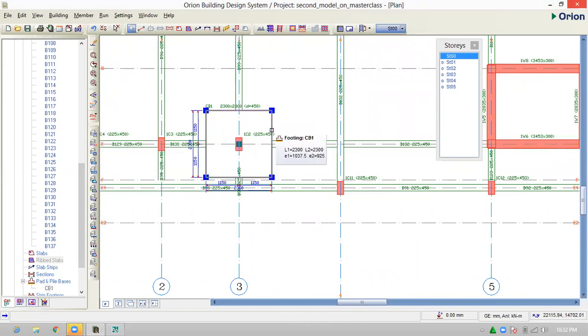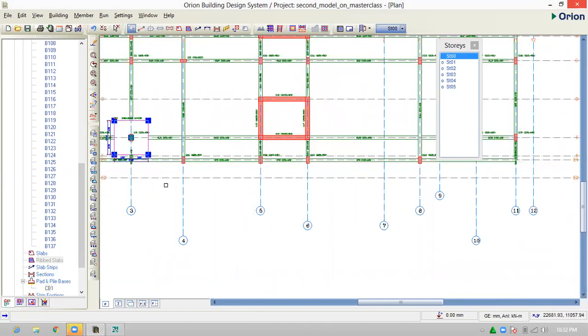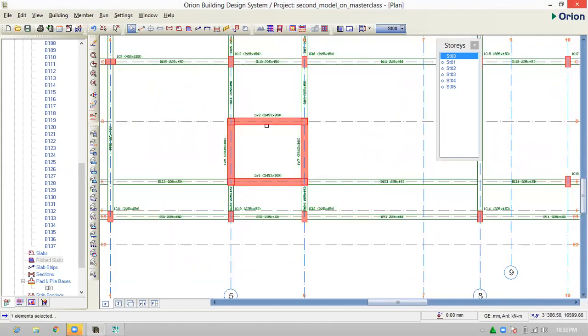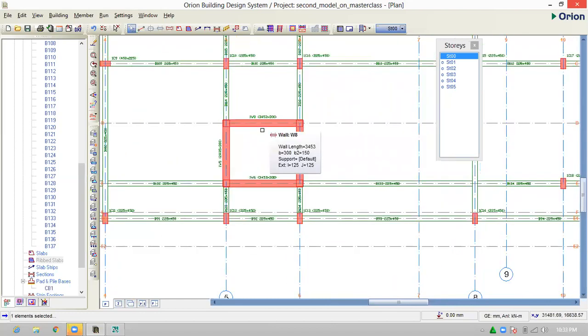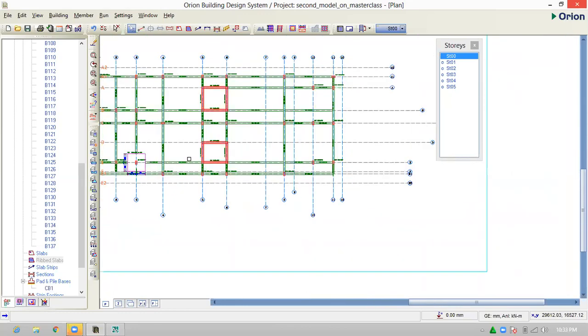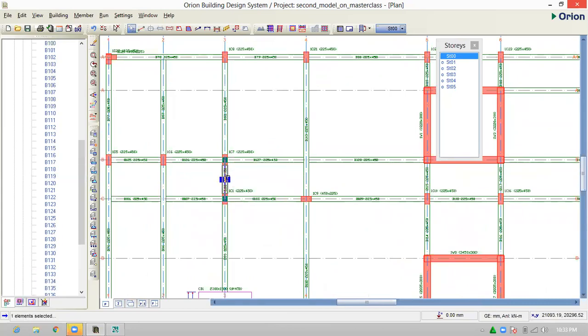Do you get it? So now by tomorrow, I'll show you how to get the details of your footing. And so now, assuming I want to add a strip foundation, I'll select this. I'll right click, select the wall or the beam. Let me say I want to use, where do I have two beams together? Okay, a beam linking two columns.